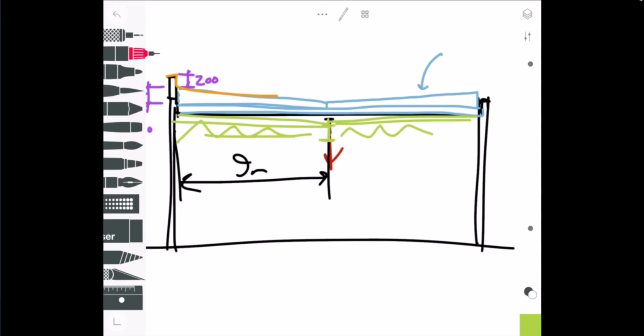The interesting thing is that we can just drop this beam in the middle so that these joists are sloped down like so. And there's really no extra cost to that. You've got to put that beam in regardless, even if you did a flat roof, you still need that beam, right?